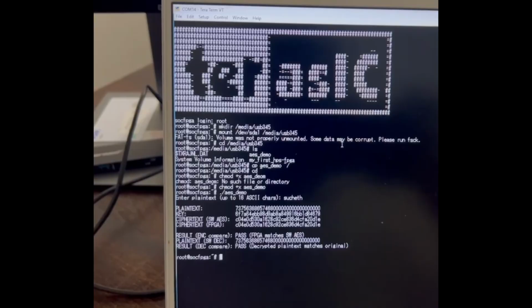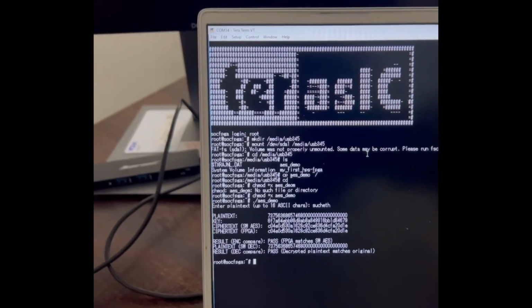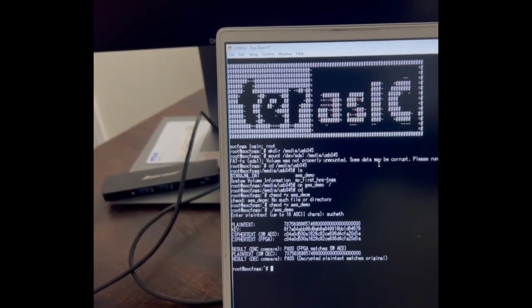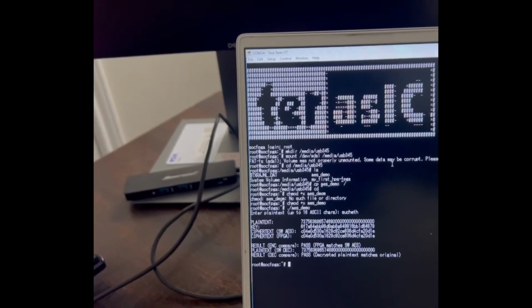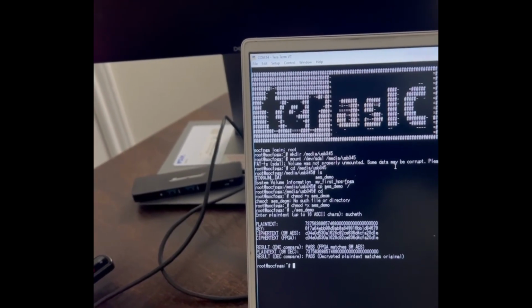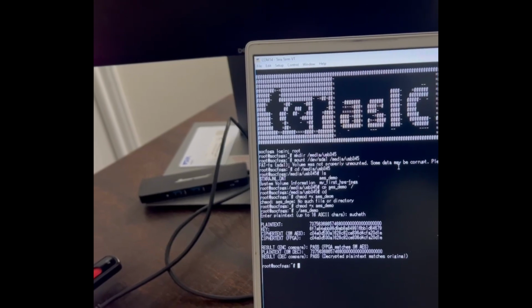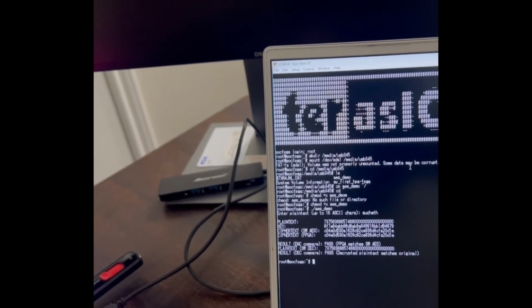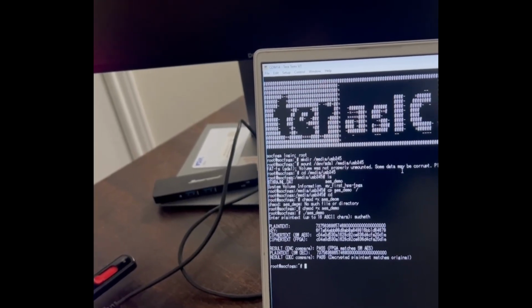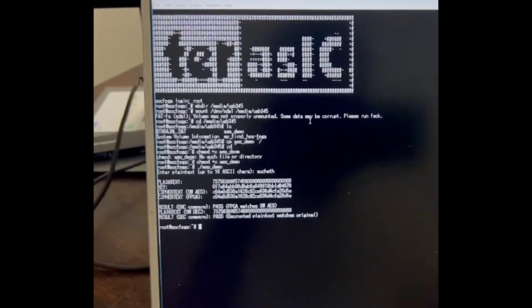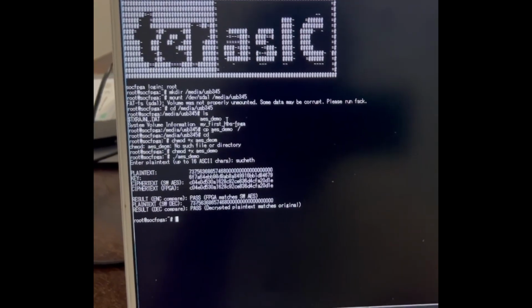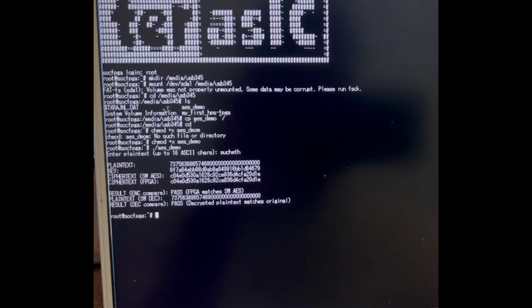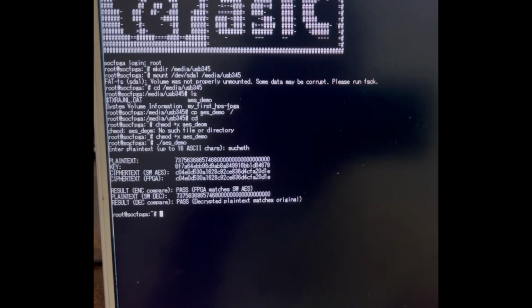We are implementing a real AES-128 accelerator in FPGA using Avalon-MM. The HPS writes the plaintext and key through the lightweight AXI bridge. The FPGA performs AES encryption in hardware and signals completion. The ciphertext exactly matches a software AES reference. I have done all the Linux commands and implemented the final project here.